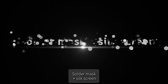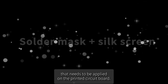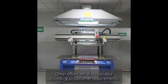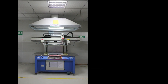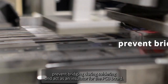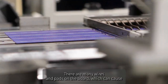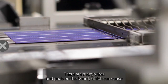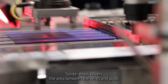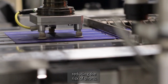Solder mask plus silkscreen. Solder mask refers to a layer of green oil that needs to be applied on the printed circuit board. Other colors are also available according to customer requirements. The main purpose of the solder mask layer is to prevent oxidation, prevent bridging during soldering, and act as an insulator for the PCB board. There are many wires and pads on the board, which can cause short circuits if they are not properly isolated from each other. Solder mask covers the area between the wires and pads, reducing the risk of shorts.